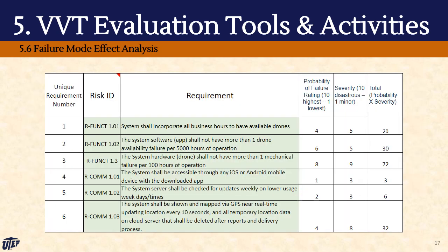Failure mode effect analysis is a systematic approach used to identify potential failure modes within a system or process and develop strategies to mitigate them. The process involves identifying possible problems, their causes, and their potential impact on the system or process. These potential failures are then prioritized based on their probability, frequency, and severity. And it finally aims to take proactive measures to eliminate or reduce the occurrence of future failures.